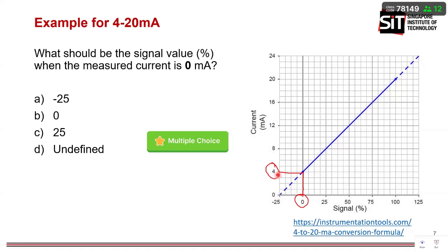This helps the industry to be more prepared for this kind of problem. Just imagine in the olden days, there could be pests, rodents, and as you know, rodents like to bite things, and they might be chewing some of your signal wires. And if the signal wire is broken because of this problem, then you know that you have to investigate, because you get 0 milliamp.